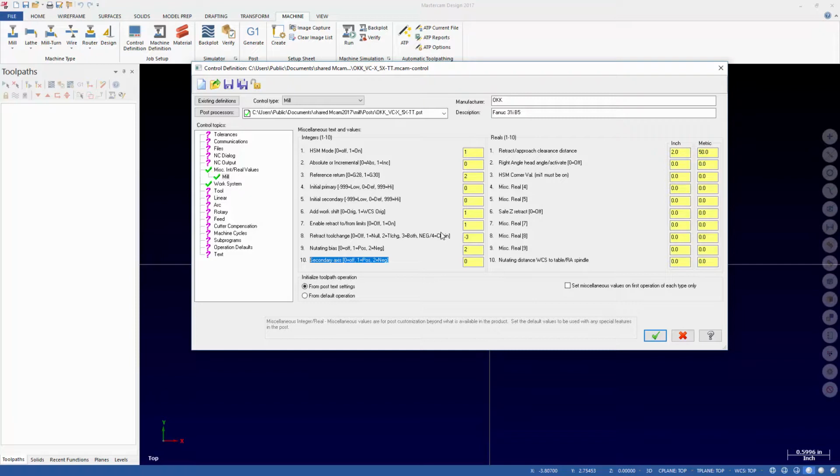There are certainly process reasons why you would want to do that. It makes restarting much easier, obviously. Maybe you've got a huge, long finishing program, though, where you're going to finish in 10 different areas. It takes you 10 different toolpaths. It's all the same tool.